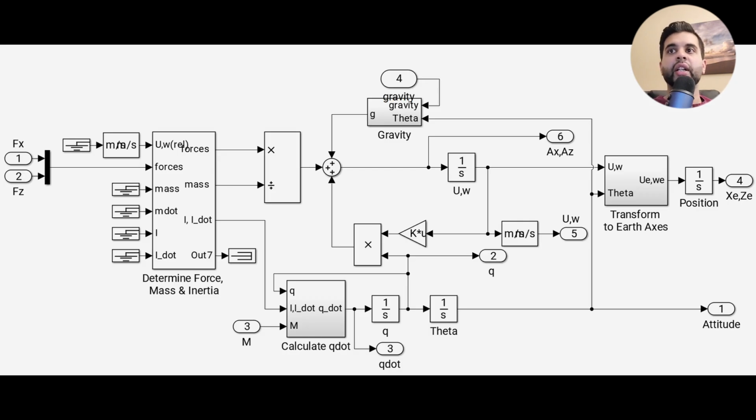So it does a bunch of calculations inside. It'll get the force, the mass, and the inertia, and then it gets the pitching moment rate, which is then integrated to get the angle here. So the acceleration becomes the angular velocity, which then becomes the angle, and then that'll be the outputs here respectively. We can see that you can get the speeds as well, and then get it to the earth axis. So that's the speeds in the correct reference frame.